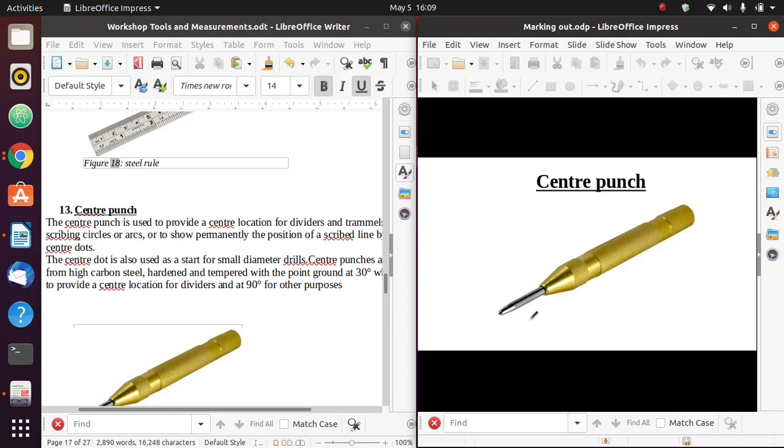It shows me the position where I drill. So how do I use it? I will go on my workpiece, and then I will take a hammer, then I will hold this place. This place is usually knurled. It has been cut. It is roughed. It has rough edges so that you can be able to hold it by hand. You hold it there, then you use a hammer to hit. That place that you hit will be the location where you have decided you will drill.